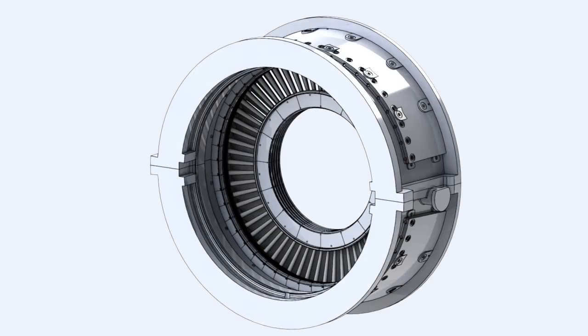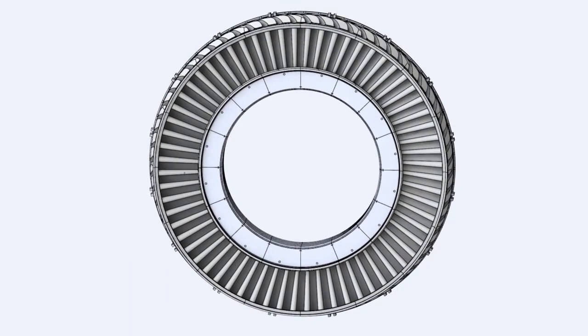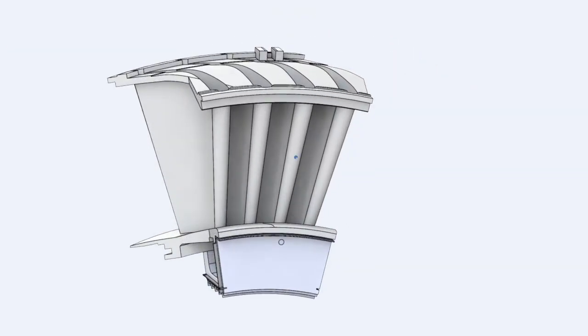The third stage nozzle receives the hot gases from the second stage rotor buckets, expands them further, and directs this flow to the third stage rotor buckets. The third stage nozzle set consists of 16 segments. Each segment contains 4 airfoil partitions. A diaphragm segment is also attached to the inner sidewall of the nozzle.